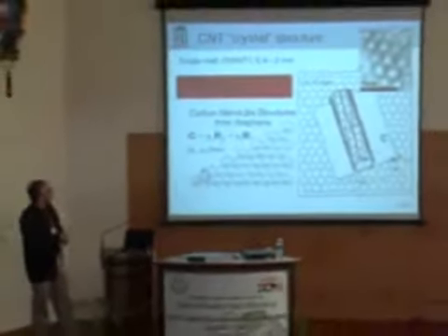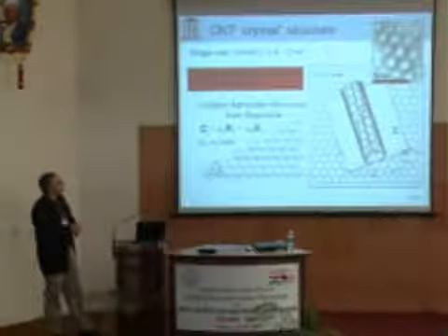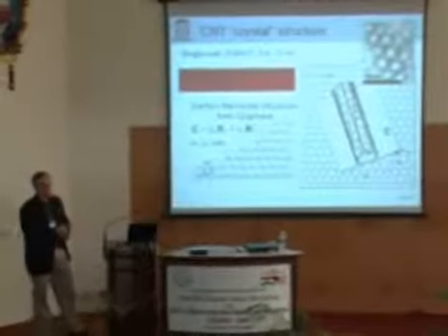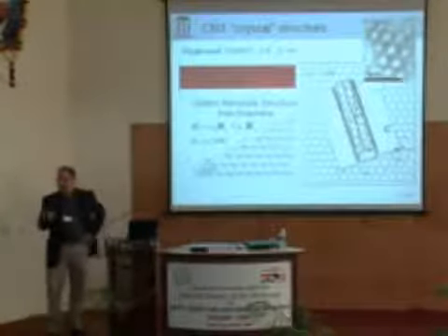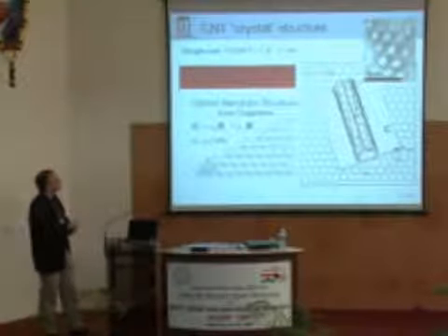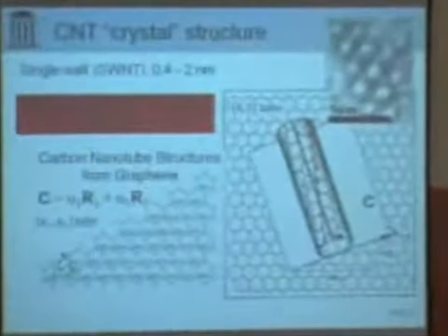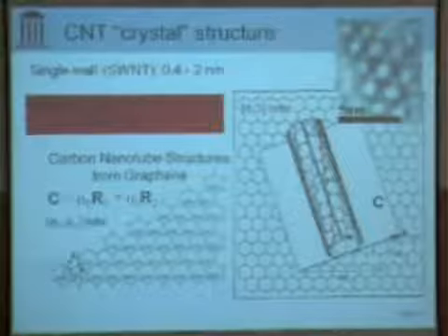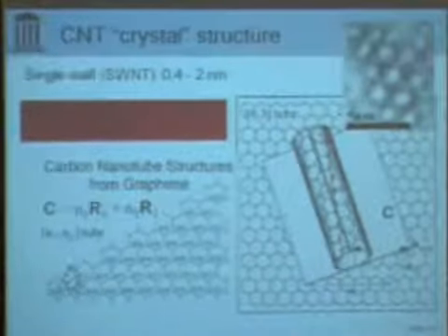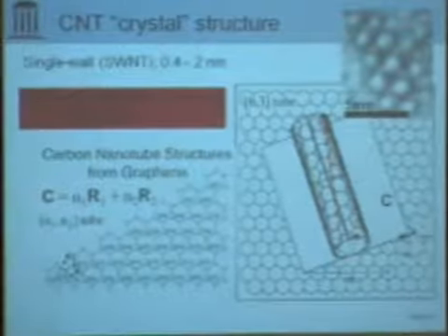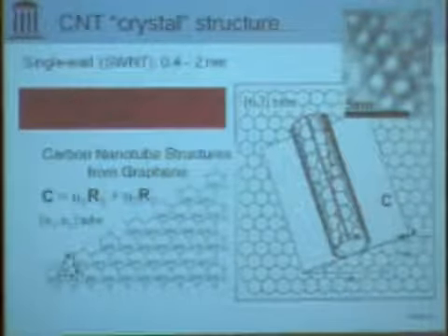The other thing to understand about the carbon nanotube is the way that the lattice wraps around the nanotube gives you something like a screw axis, or the chirality of the nanotube. And that can change, for example, how this nanotube would sit on the graphite lattice underneath it. And it defines an angle that that nanotube would sit on the lattice. And that's going to be important for us to understand. There's two types of nanotubes I'm going to talk about.